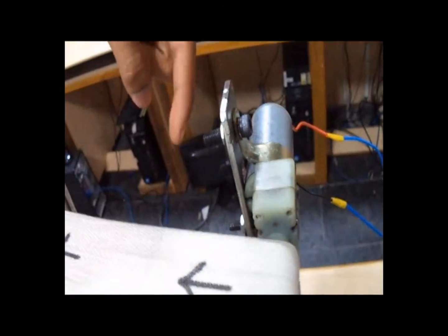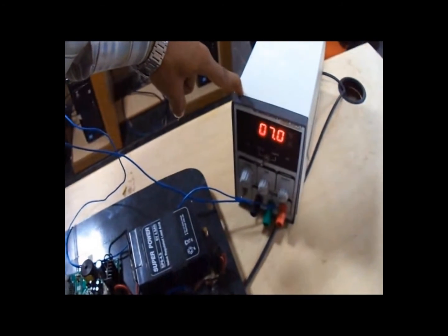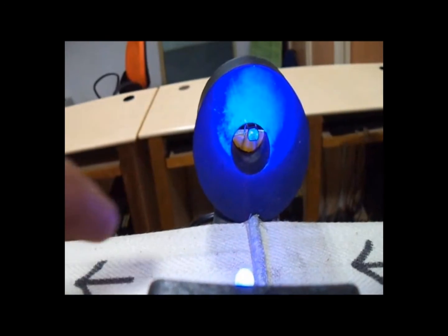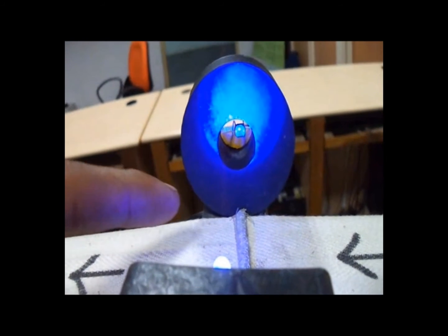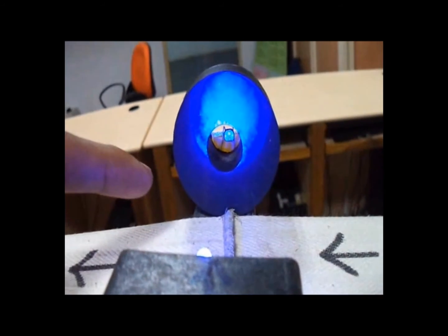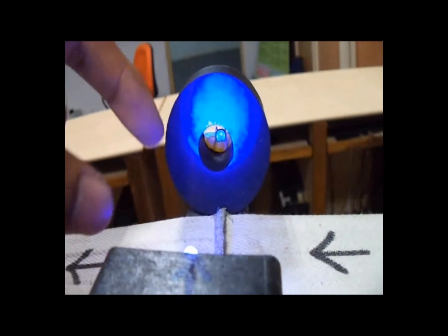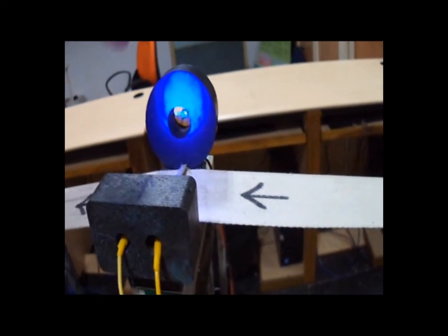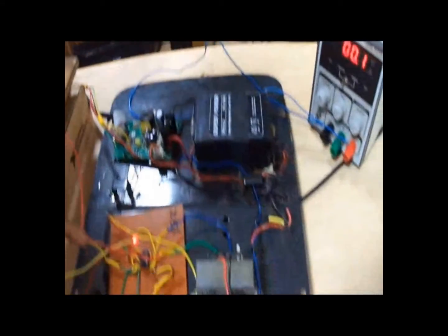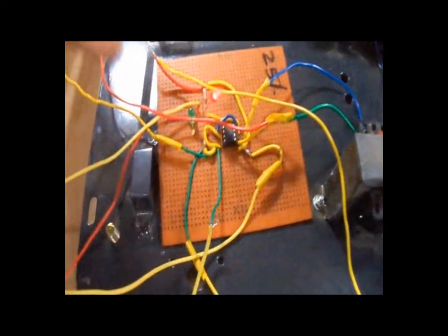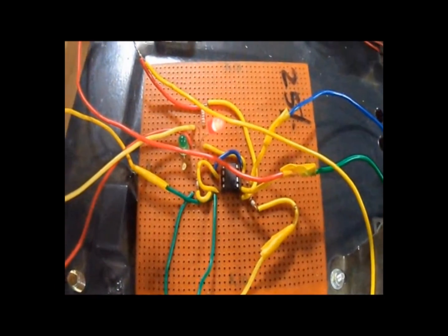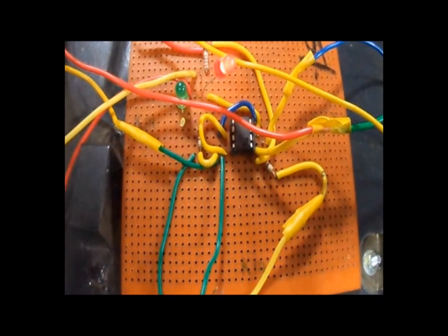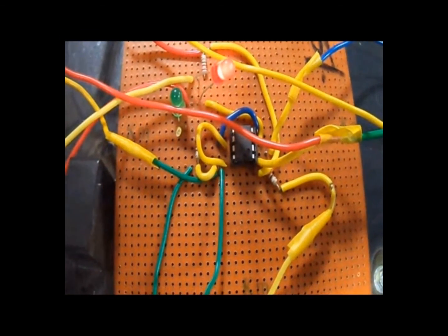This is a 24-volt DC motor, and this motor is driven by a DC regulated power supply, and this supply is used to run the conveyor belt at constant speed. This is the sensor unit, which consists of an LDR and a light source. The light is continuously made to fall over the LDR. When the light falling on the LDR is interrupted by an object, then the signal will be sent to the processing unit. The processing unit consists of a 555 timer circuit, and this circuit will analyze the signal and the corresponding digital signal will be sent to LabVIEW through the shielded connector board 68, that is, the SCB.